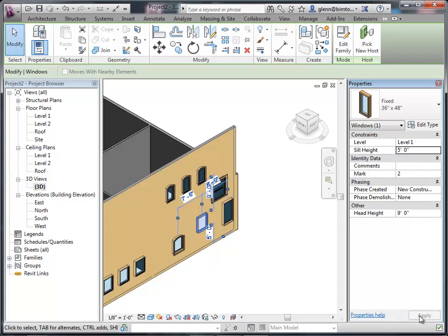And we can go through and do something on the view to raise the cutting plane in that area so you can see it. For example, a real classic case that gets you in trouble is these guys up here, all these little clear story windows. If you look at the floor plans for this room, they never show up because we're always looking at the sheetrock and metal stud layer here. We don't actually see those.